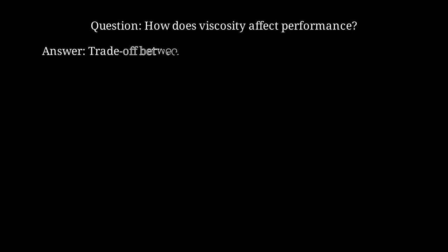An important design question: How does liquid viscosity affect both optical quality and response time? Higher viscosity liquids are more stable against vibrations and gravity, improving optical quality. But they respond more slowly. Engineers must balance these competing requirements.